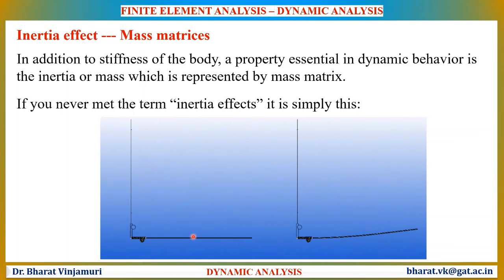On the left side, you see a static analysis where the rotation is applied to the handle. This is what would happen if you apply the rotation to the handle very slowly. This is known as the static domain. The load is applied so slowly that you can basically ignore the effect of inertia.